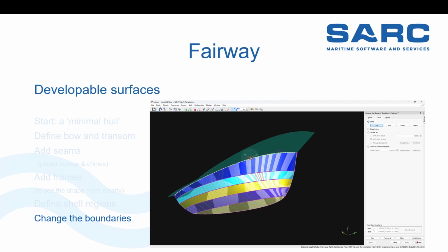This developable plate option, but can you also integrate it in an existing hull if you want to make the shell shape behind the bow thruster? Yeah, it will change, of course. If it wasn't developable, you cannot have a double curved plate and make it developable, because then it will no longer be double curved. No, that I understand, but if you have the bow thruster pipe, and I'm looking aft, and you have your water line running like this, then it could be that you make a scallop behind it, which is developable. Yes, you can.